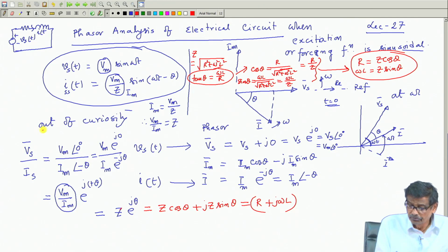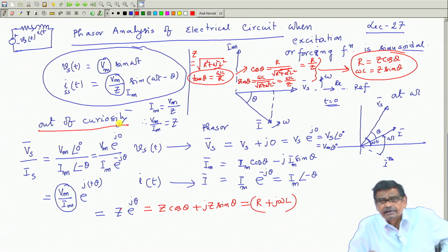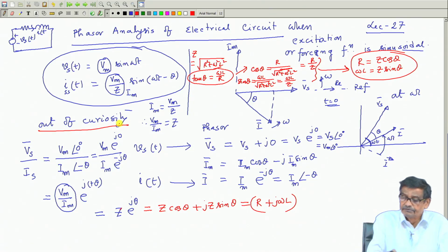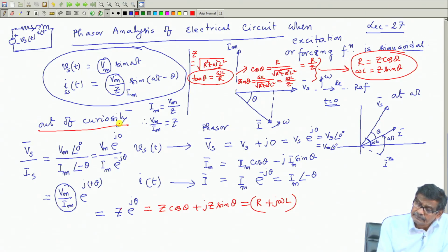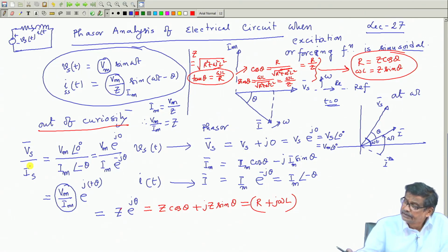So, what I told you, I just represented sinusoidal quantities as phasors. The angle between phasors does not change, it comes out to be theta, and then I could represent the supply voltage as a phasor, V m peak value at 0 degree, and the current, of value I m, will lag the supply voltage by theta, that is minus theta.